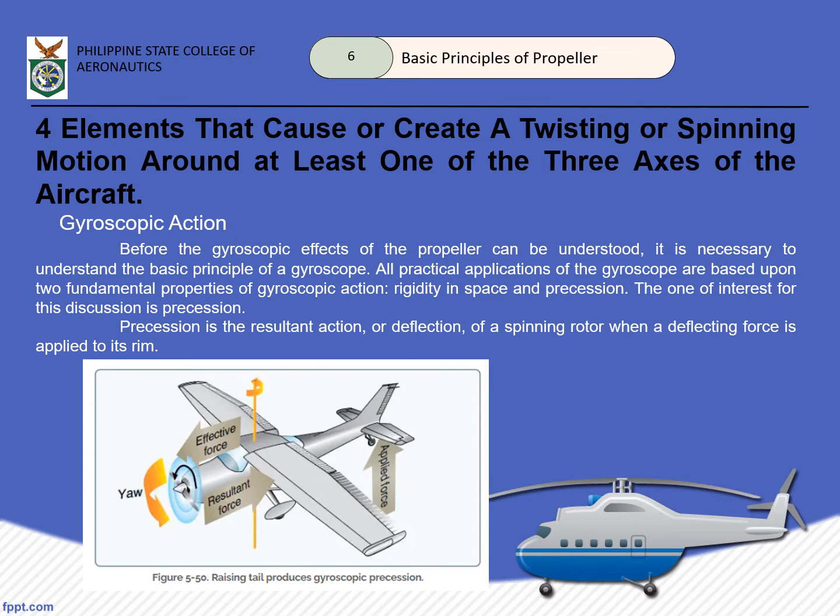Let's say our propeller is turning to the right. Then we apply an upward motion, which is by what? Pitching the nose up. It will give us a resultant force that pushes the nose of our aircraft to the right as well. So, where does this significantly apply? Diba sa example natin, that right motion can be countered naman by the left turning tendencies.